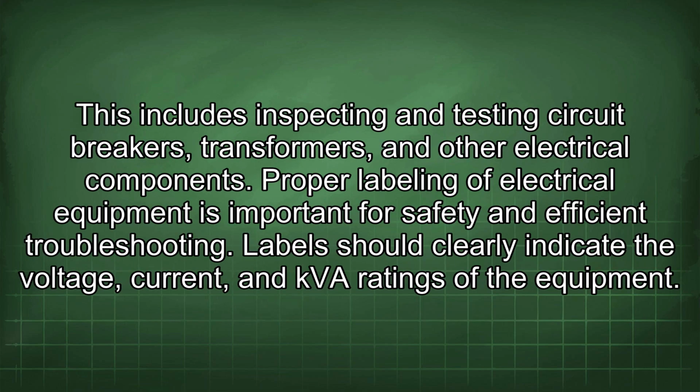This includes inspecting and testing circuit breakers, transformers, and other electrical components. Proper labeling of electrical equipment is important for safety and efficient troubleshooting. Labels should clearly indicate the voltage, current, and kVA ratings of the equipment.